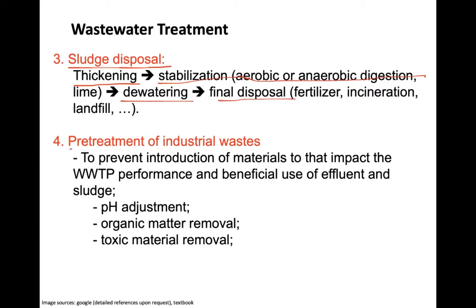As we said, the wastewater treatment plant can accept whatever comes out of households or out of industry. But what people also recommend is that industry pre-treat their waste before they send it into the treatment plant, mainly because, as we showed earlier, the slaughterhouse and the tannery can generate very high BOD.